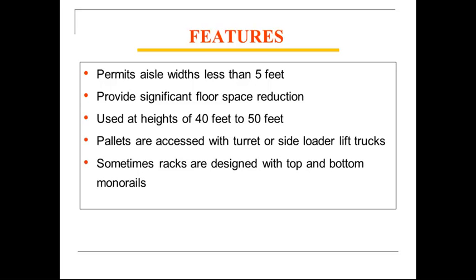Provides significant floor space reduction. Used at heights of 40 feet to 50 feet. Pallets are accessed with turret or side-loader lift trucks, and sometimes racks are designed with top and bottom monorails.